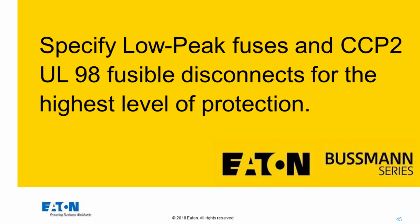I actually compared the area taken up by a CUBEFuse in its holder to a Class J fuse in its holder, and the CUBEFuse was like 15% the size. I thought that might be wrong, so I went out to my garage and got a sample of each one and measured them, and it's accurate. Those two products are extremely space saving. Especially the CUBEFuse, when you compare it to a Class R fuse, it's a fourth the size.